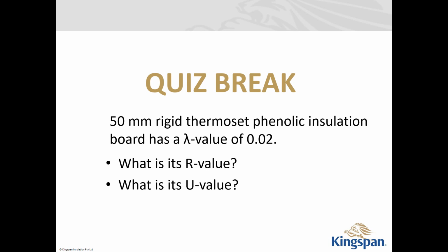Yeah, the numbers are actually small, so with just having a number, you're not comparing it. With normal house wall insulation, how does that compare to a cool room? Okay, first, before we move on to that, the smaller the K value, the better the R value. The K value is going to be the inverse of the R value. So we've got an R value of 1.25 there, but we should have 2.5, shouldn't we? Yeah, we should have 2.5.